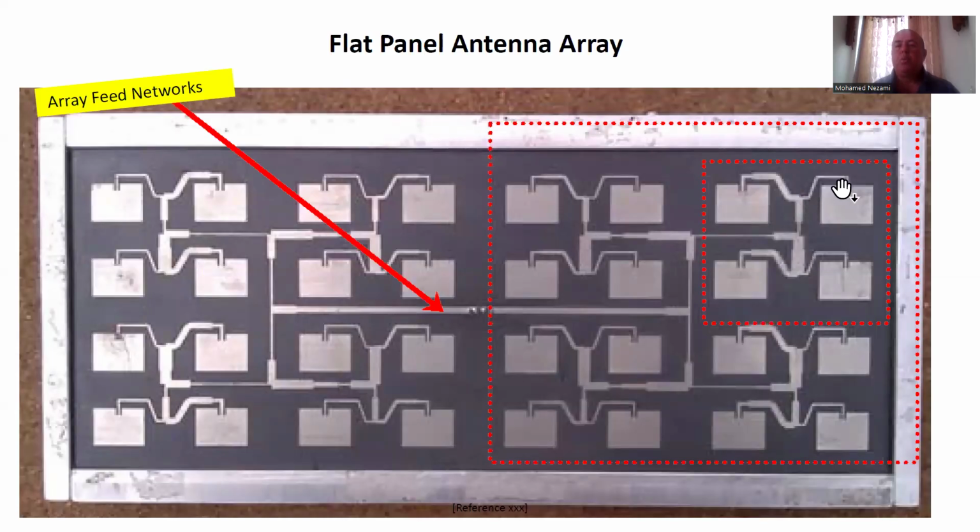As you know, the width of these is proportional to the impedance. You can see that this is a thin line in here. That means this is a higher impedance than this line in here, okay? And this line in here is a thin line. You can see that this is an asymmetrical power splitter, where a little piece of the power is going into this high impedance line, while most of it is going into this low impedance line. And you can see that this here is basically where we start out with the source.